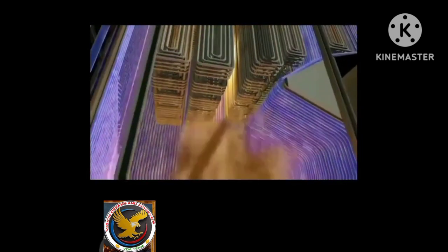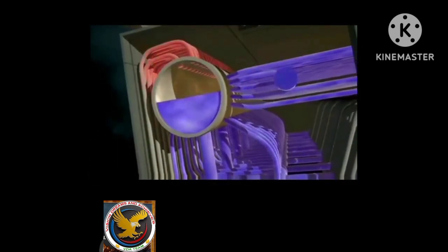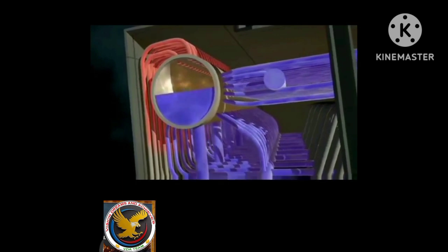A network of 2-inch tubes line the firebox walls, and burners force feed a continuous supply of combustible fuel into the ultra-hot firebox. Eventually, the insides of the firebox burn so hot that its surrounding steel walls would melt if not for the tube-lined walls of liquid water. At the point in the cycle when the liquid water turns to steam, the steam separates and collects at the top of the steam drum.